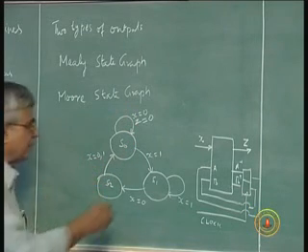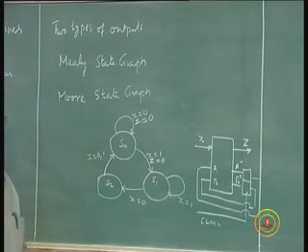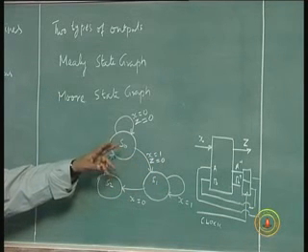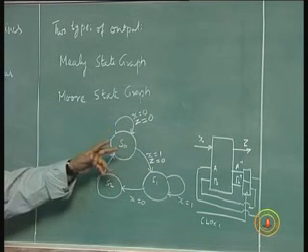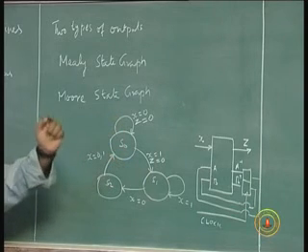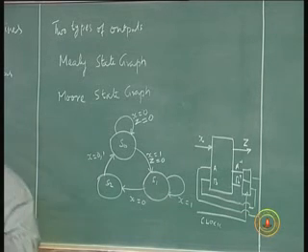So I may put Z as 0 here. That means as long as the circuit is in state S0, this output is 0. But I should specifically say this here and here. For each arrow I should give an output value also. It is in a Mealy machine where the output is defined as dependent on the present state and the input condition.